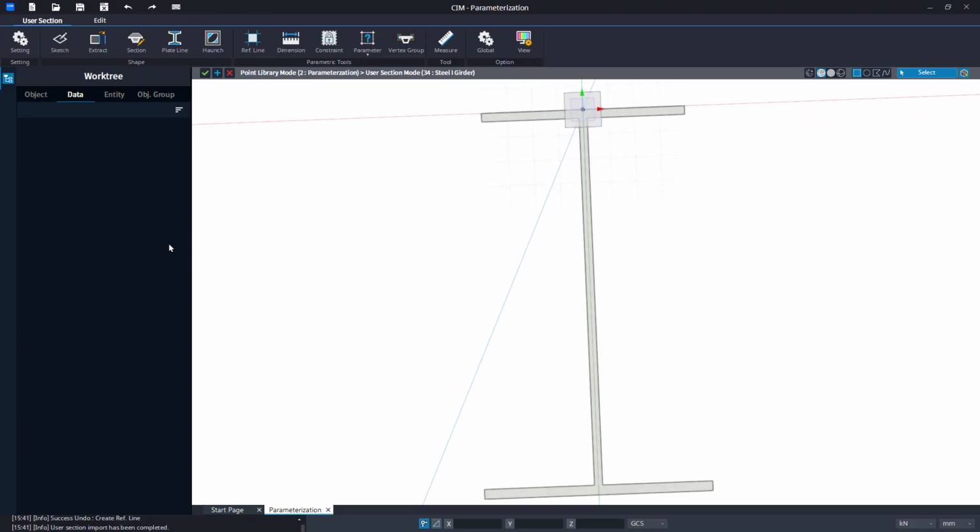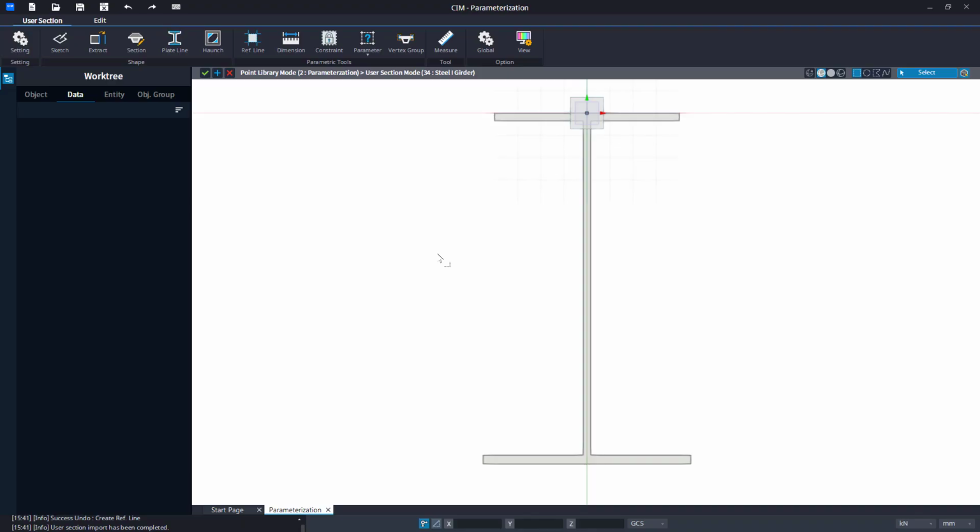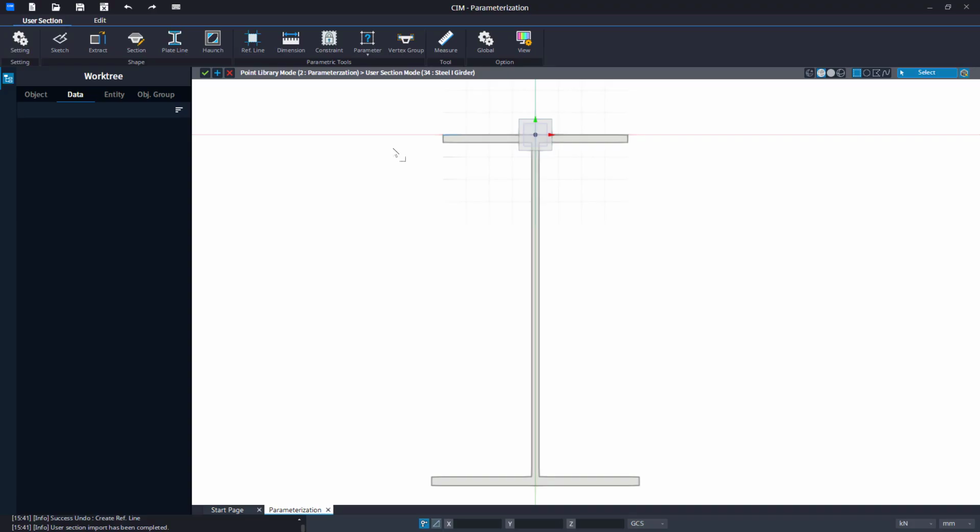We'll go to it. Over here, we will be using the coincident type of constraint for locking all the vertices of this Steel I-Girder section. Apart from that, we will be choosing the fixed constraint at the reference location. And in the dimension line, we will be using the horizontal and vertical dimensions only. So now let us first define the reference lines.